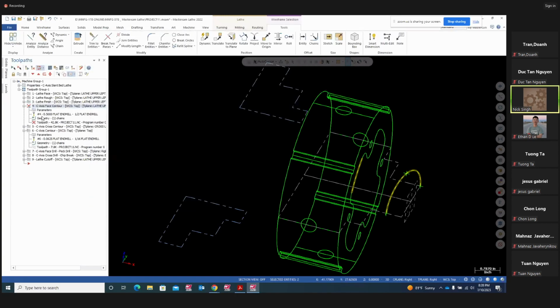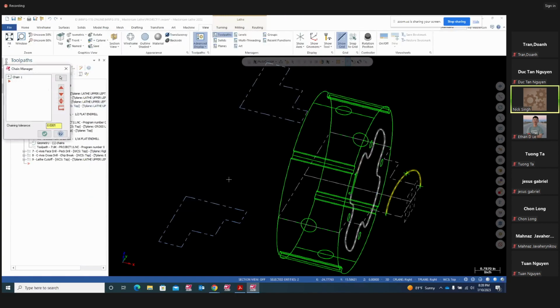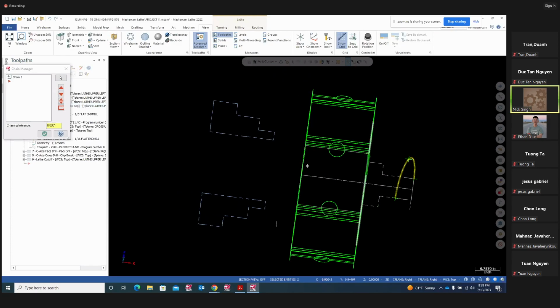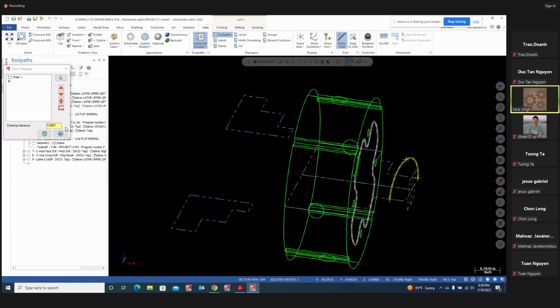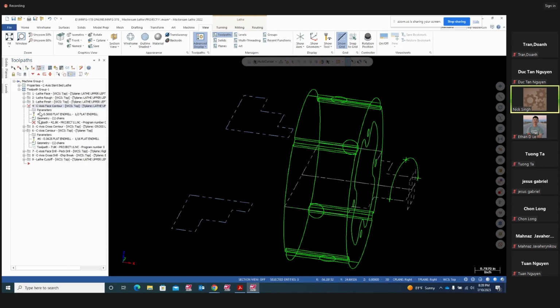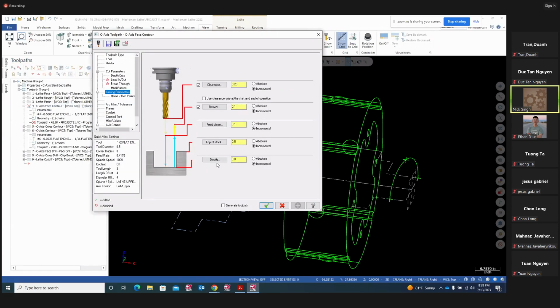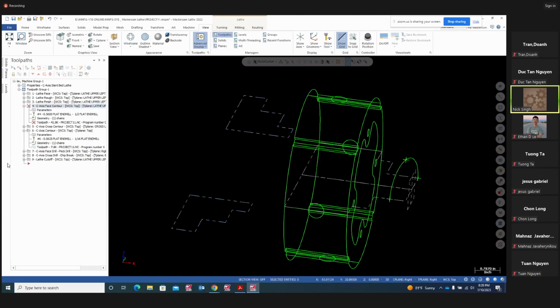If you look at here, under your geometry is right here. So when you select that geometry at a full depth, guys, in that case, your depth is going to be 0 because in incremental, your depth is going to be 0 because we already selected that geometry at that depth. Regenerate that. That is going to be your toolpath.